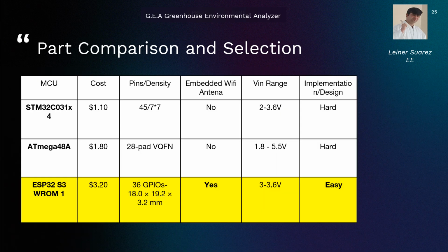Choosing the microcontroller, we chose one that has an embedded Wi-Fi antenna. This was the most important thing to us since we're going to run our application over Wi-Fi. It's going to be connected to a server, and it's going to be connected to another microcontroller. The ESP32 has ESP-NOW that we can also use. It needs a maximum of 250 milliamperes if everything is working. It might use up to 350 milliamperes, but we can provide that current with the previous voltage regulator.